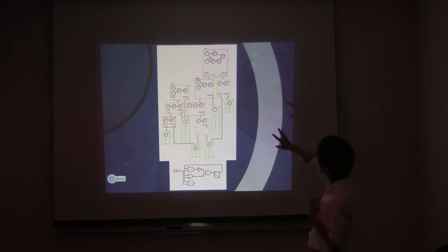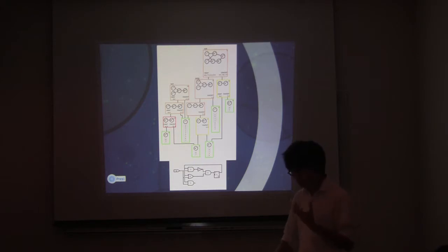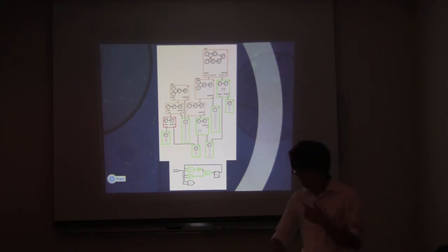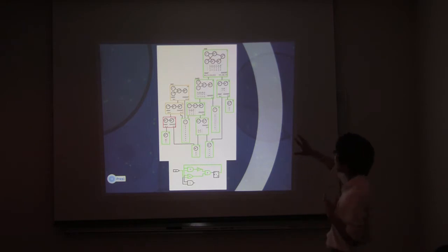As for the other 2, because those structures exist in the circuit, those nodes are combined and are therefore marked alive. We keep going up the tree until all possible mappings have been made. All possible mappings are made when any unsolved node's child nodes are not both alive. So in this case, for the unsolved node, we have either one unsolved or one marked dead. So those cannot be combined anymore.